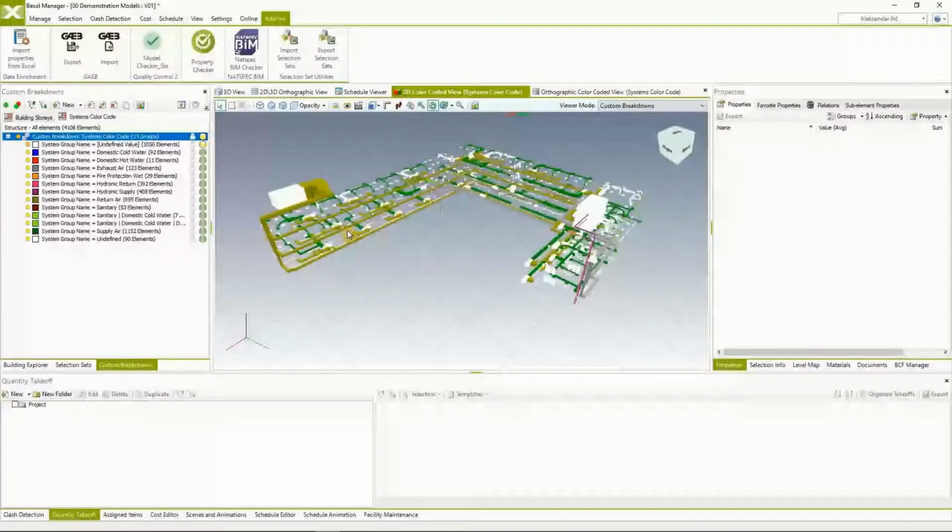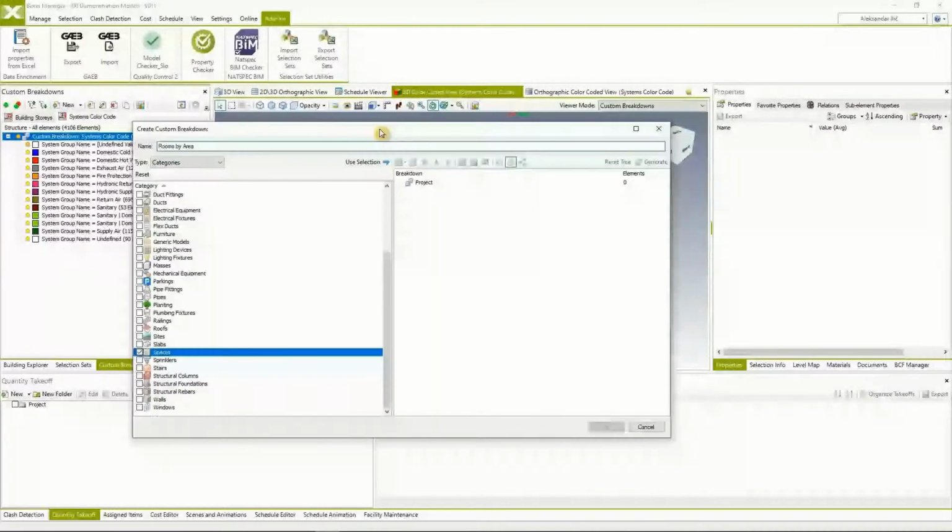We can also further utilize imported predefined selection sets that are sorting rooms by area, let's say. So basically, we have imported the selection sets that are sorting rooms by area, but we also have a CBS template that will color all these groups of areas based on the property area. So we can now import the template and show how it looks.